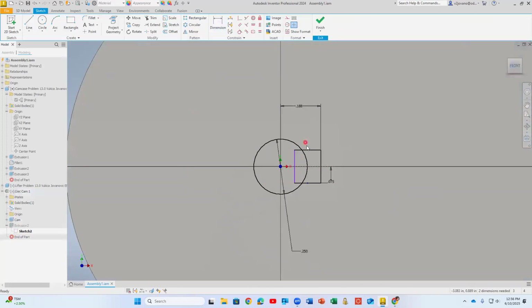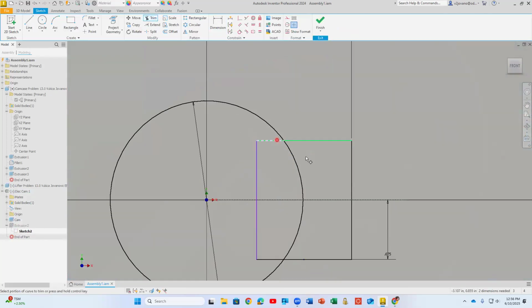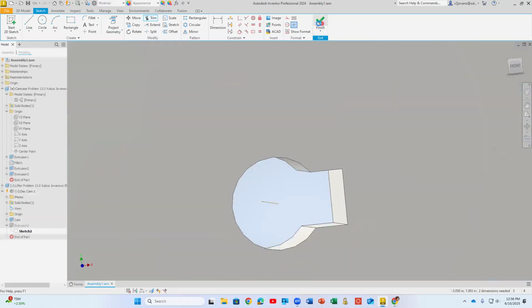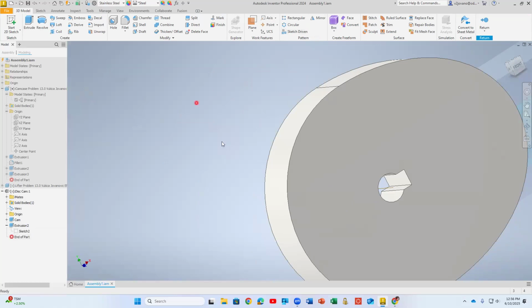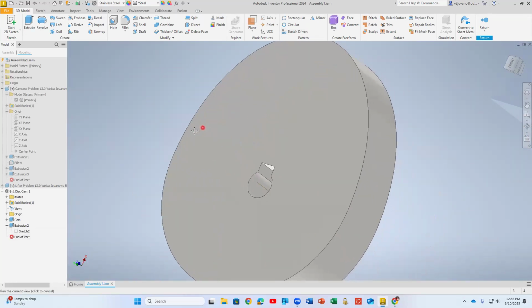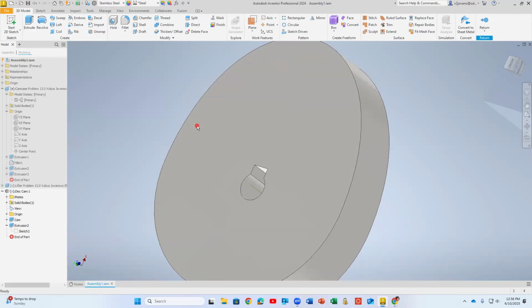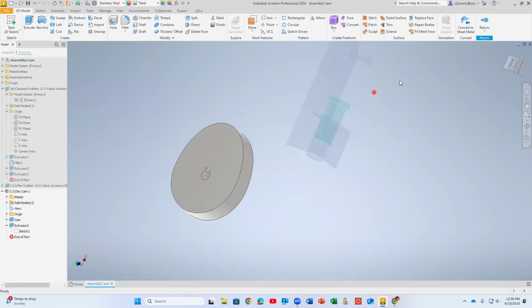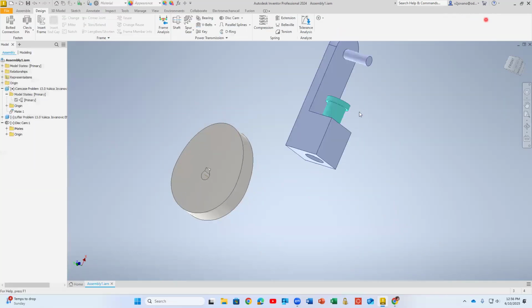The other way is like I will go and clean that up. If you really don't like this looking like this, you can just say, okay, no problem. I'm trimming, but you might have an error because after I finish this, I did extrude. So it might tell me complaint, but here it figured it out. So you see my cam now has this small gap. So, and if you say return, we're going back to assembly.